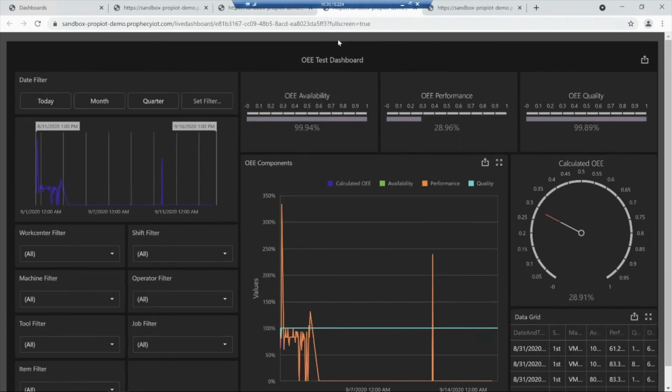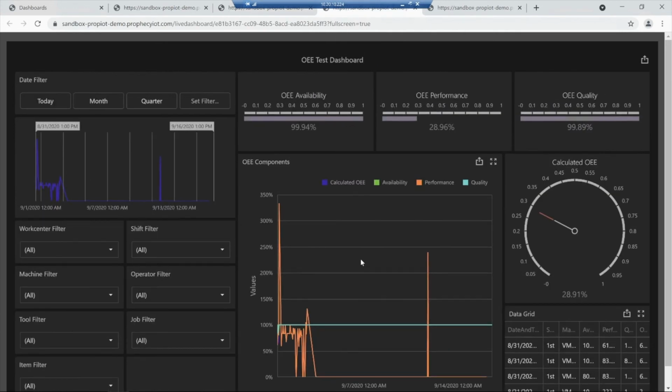So next one we've got after downtime is OEE. OEE stands for Overall Equipment Effectiveness, and it's really handy for finding out if your machines are performing up to par. An OEE is a number that's calculated from availability, performance, and quality factors, and they give you a number between 0 and 1. World-class OEE is typically in the 0.7, 0.8 range. And again, it varies by industry, by machine, by your own company's policy. Different types of studies would have to be done to determine what the optimum OEE would be for a given job, machine, task, part, and so on. But that exceeds the scope of what I'm talking about right now.